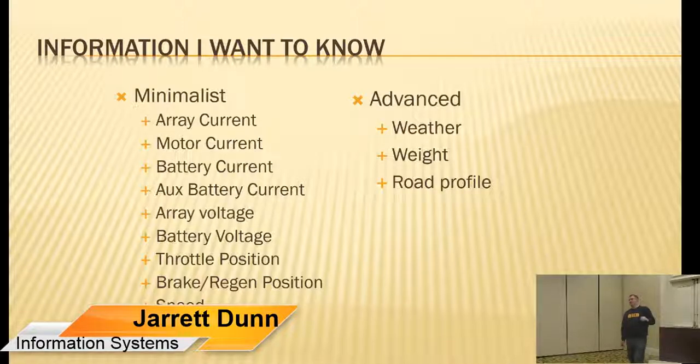I measure the throttle position. This goes back into knowing your drivers. Being able to look back and see why driver 1 was different than driver 2. The indication is generally how fast they're hitting the pedals, both the gas and the brake pedal. So generally you want to be very smooth as you're driving a car. You want to slowly and gradually apply the throttle to get to the speed you want to be, and then you want to stay there. You don't want to just slam the pedal down, get to where you're going, and then rapidly let off, slow down, and go back and forth. That's about the least efficient way to do it.